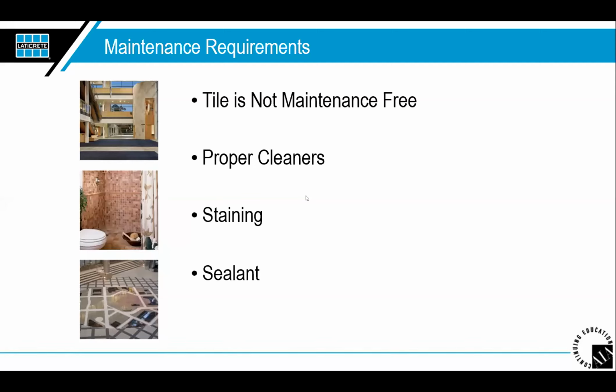But I am a big fan of telling people, if you want the highly modified products, with a lot of latex content in them, or even epoxy content, move into those product categories. For example, we have epoxies, and a lot of one-step grouts out there that are new chemicals. Then you also have things like urethanes. Urethanes are another great product for hardness, but there are different curing processes with urethanes versus epoxy. So it helps to know how fast you want to move through the project as well.